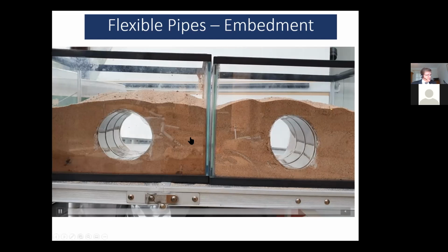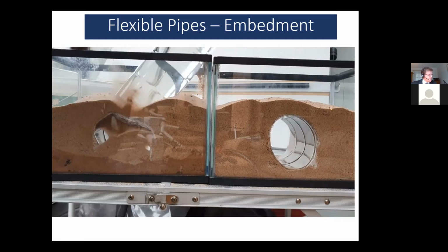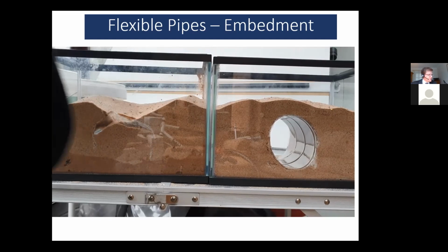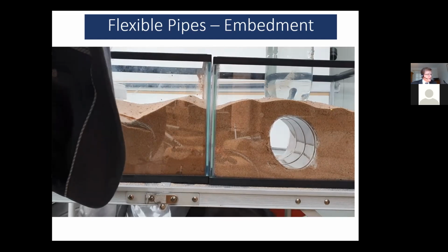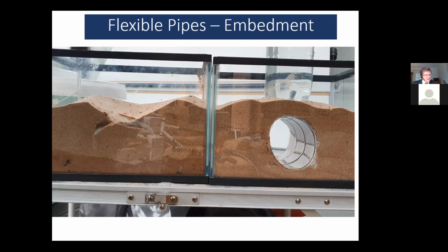So as you've seen, I didn't compact this side a lot, but we'll see what difference it makes. This is good quality sand. This is uncompacted, and we're going to load this up first, and we're going to use a 2-litre bottle of water. So it weighs approximately 2 kilograms. I'm trying to place that in place, and over she goes. It's not going to handle that load. The compacted side, however, can. So just that bit of compaction has made quite a difference to support that the pipe is receiving from the surround around it.